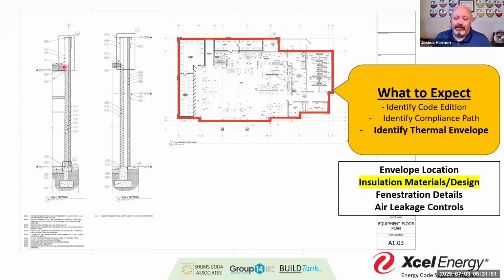And sometimes we get what I call flippant answers to some of those conversations. Like I had one last week where the answer was all insulation shall be considered part of the thermal envelope. Are we sure? Because this is a multi-story building, and you've got sound attenuation between offices. So do you really mean all, or do you mean a particular assembly? Right? And again, drive back to those details.